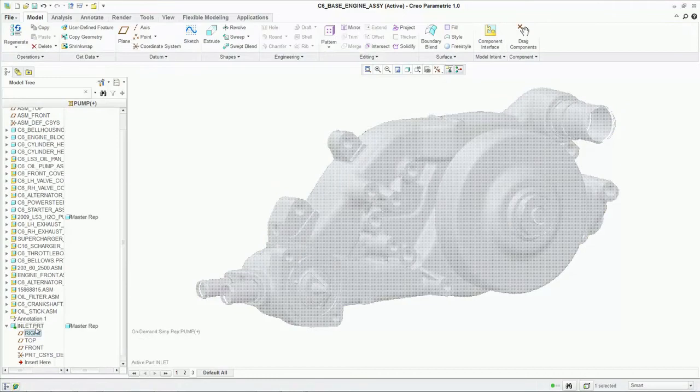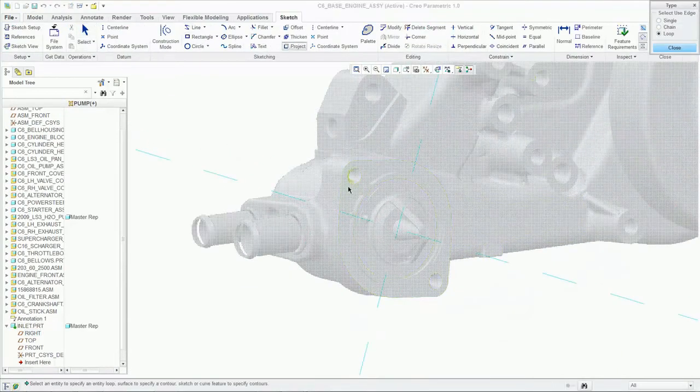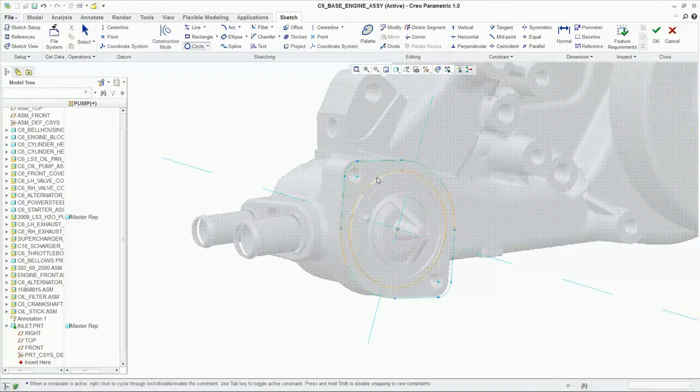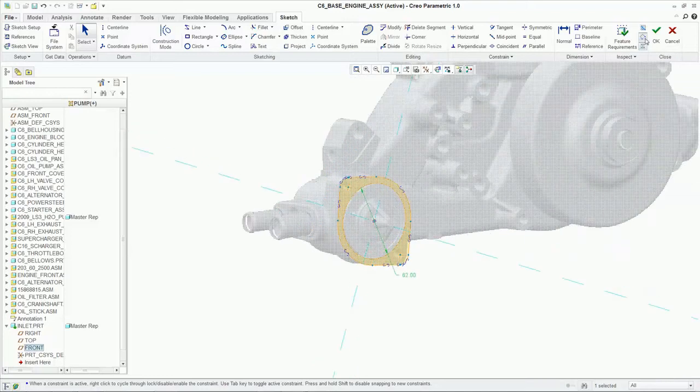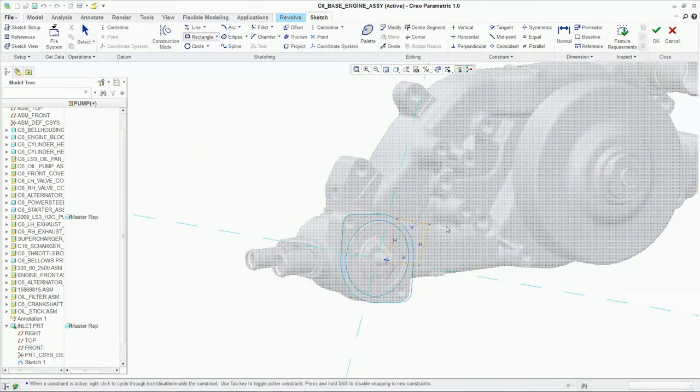Here, we're just defining the datum plane on which to sketch the new part. We'll sketch a circle on the plane to define the outer radius, and then we'll sketch a rectangle and a circle on the normal plane. We can then delete the appropriate segments that will leave us with a semicircle cap once we revolve the sketch about the defined center line.